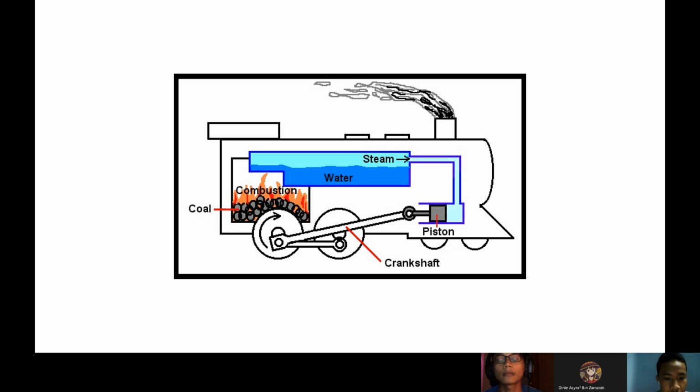Equalizing lever, part of the locomotive's suspension system, connects to leaf springs free to pivot about their center, which is fixed to the frame. Its function is to even out the weight carried on adjacent axles on uneven or poorly laid tracks.